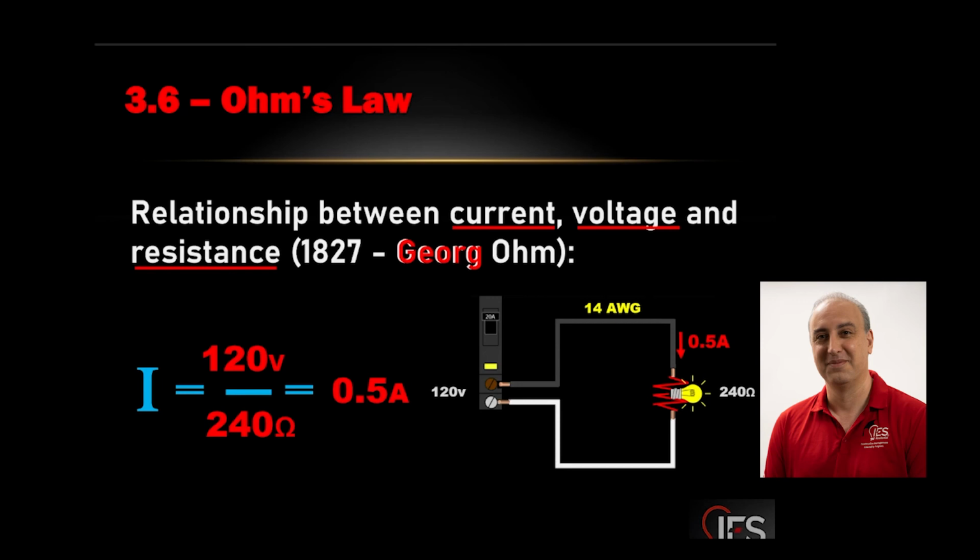And 18 amps on a 14 gauge wire, resistance starts heating it up. Now we understand electrons moving. That's why the code has those numbers that we can't go over, because we'll heat up and burn the wire. This is why